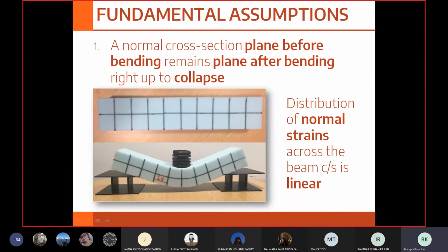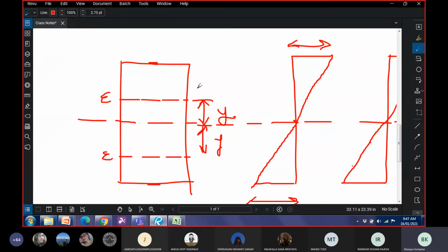Okay, so I may do it at various points. I may just do the same thing, and what I'll get is that the strain at a particular distance from the neutral axis is exactly the same as the strain below the neutral axis at the same distance. In the example that we are looking at, the increase in dimension along this line is going to be the same as the decrease in dimension along this line along the length. So the strain at these particular levels is the same.